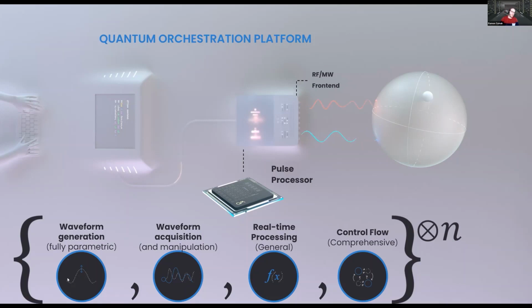So basically this Gaussian envelope you see here would be streamed out of the pulse processor, and as it exits, it will be modulated by 100 or 200 megahertz or whatever. These frequencies can be tuned. The phases are parametric. You can do full frequency modulation. You can do chirps, not only linear chirping, but any arbitrary frequency modulation, any arbitrary amplitude modulation.